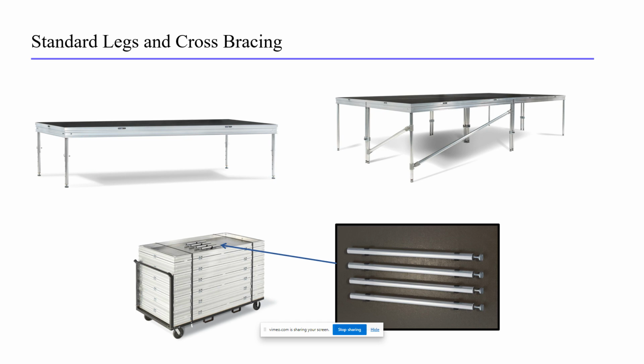So we talked about standard legs. These are by far the most common style support, offering the lowest cost up front, highest flexibility, and smallest storage footprint. Note you can see in the slide here that the legs are able to be stored inside the platform cavity, either loosely or in flashlight clips where the platforms are stacked on carts. Standard legs are offered in either fixed or adjustable height range, but require bracing once you reach heights in excess of about 30 inches in most applications. Note the photo in the slide here shows those diagonals.